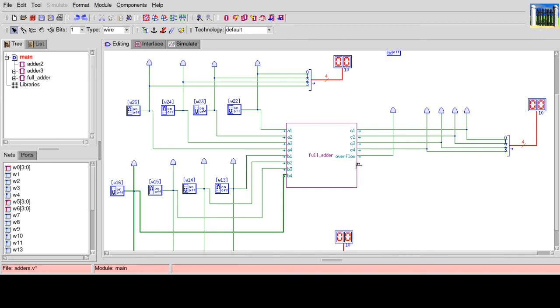Finally, out on the other side of the adder, you get 5 bits coming out. Why? Because you get 4 bits for the answer, and then you get that overflow. If you want to confine the numbers that go in and come out to 4 bits, unfortunately, when you add two 4-bit numbers, the answer can be 5 bits long. That final 5th bit is what's called the overflow. It's the carry that would have gone into another column, but we didn't have one. That's why I put it off a little bit to the side. So that's what you're looking at here.